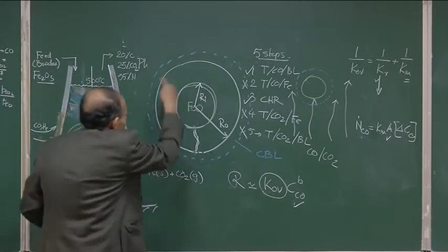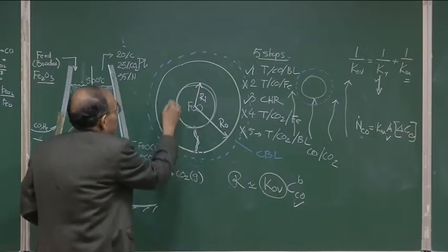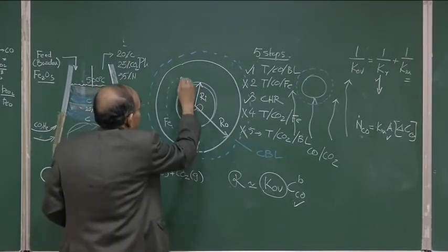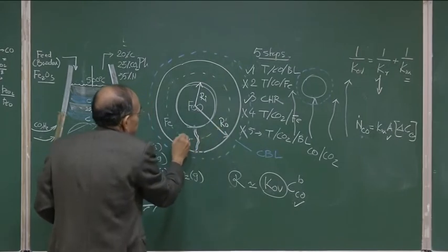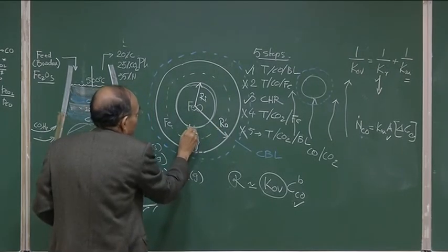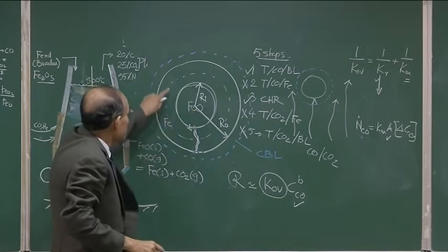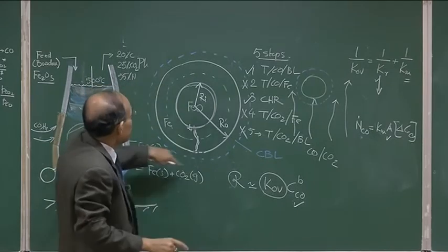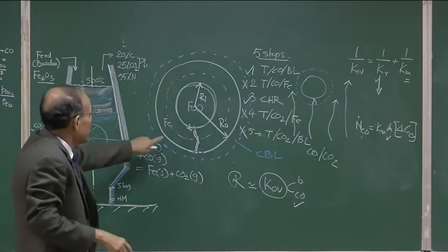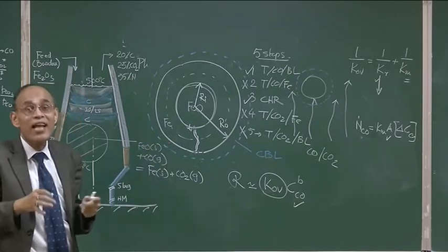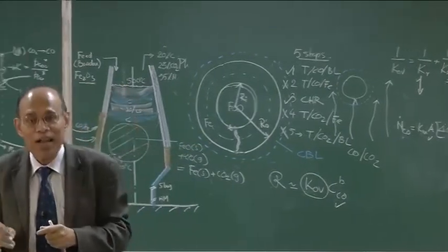This sort of a scheme that I have written, where the reaction front at a time t is equal to this, at another time is equal to this, where the reaction front is parallel to, or maintains the same kind of contour as, the initial shape of the particle, we call it a topochemical model of reduction.